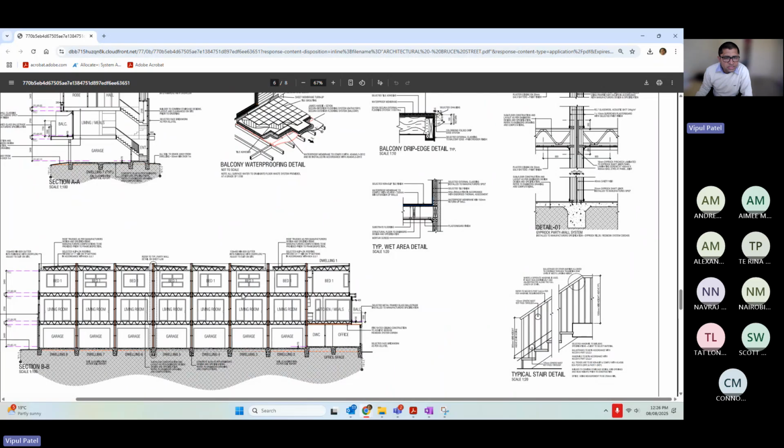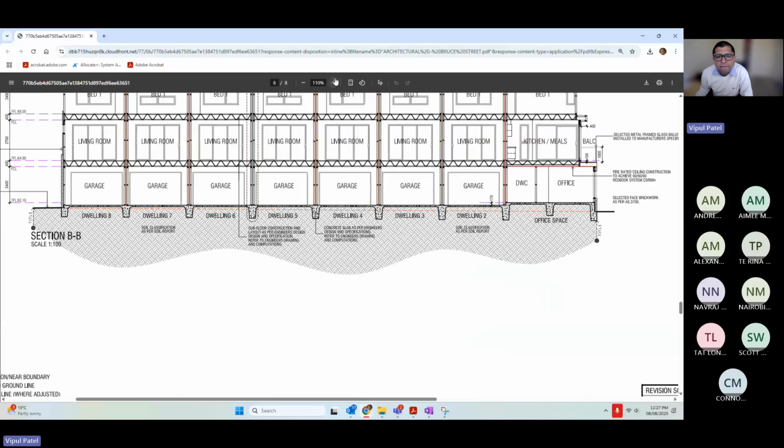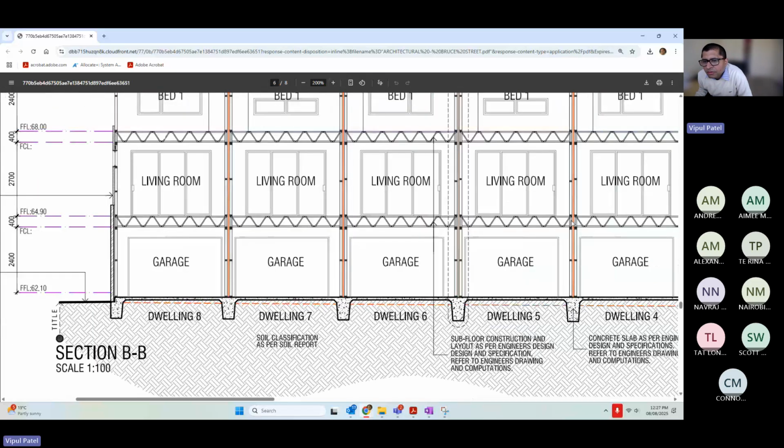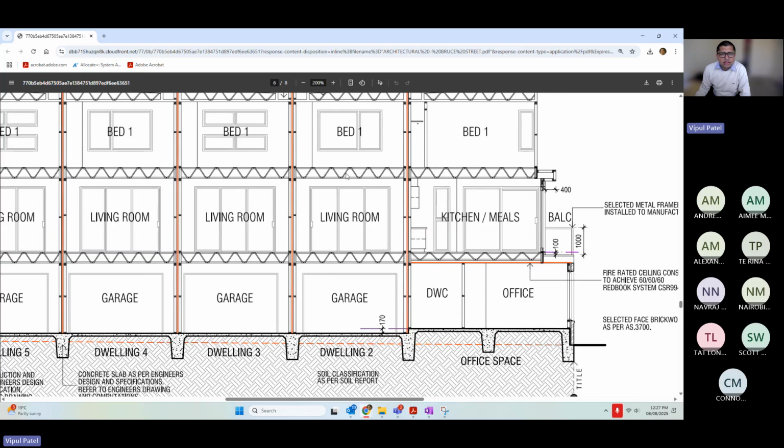So if you are talking about this load width from here to here, if you draw the line in here, someone might say, what about these 2 meters on this side? No, there is a beam sitting here. I'm not sure if I magnify, you may not be able to see. There are two different beam sittings. You see, there is a partition red line, and there are two beam sittings on each side of the unit. So these beams that we are designing here only carry half of these. These beams will carry half of these. They don't need to interfere with the neighbor, and therefore they are separate.